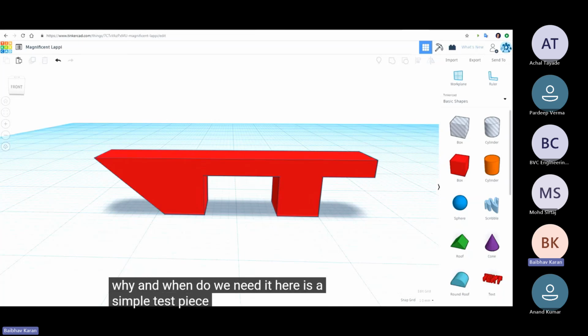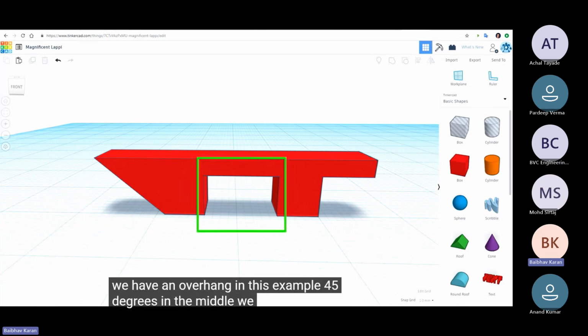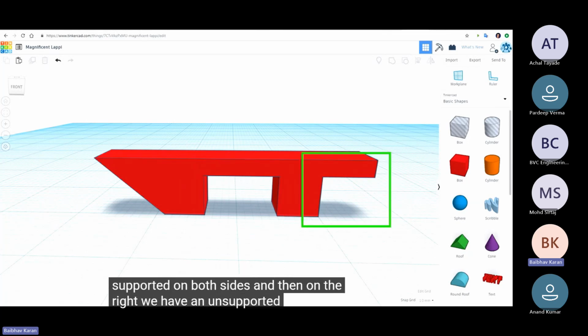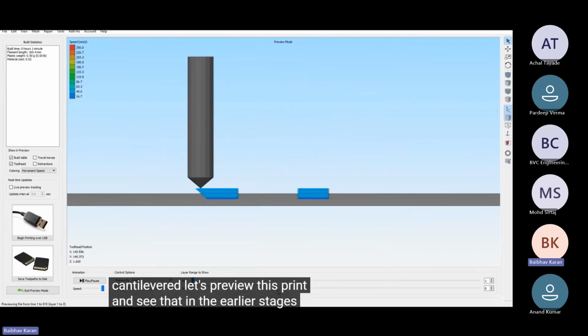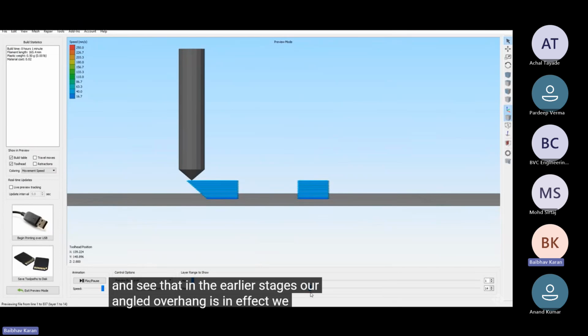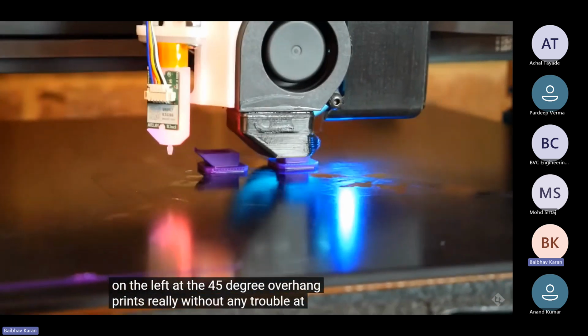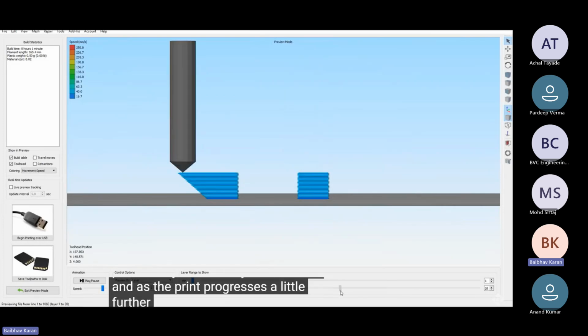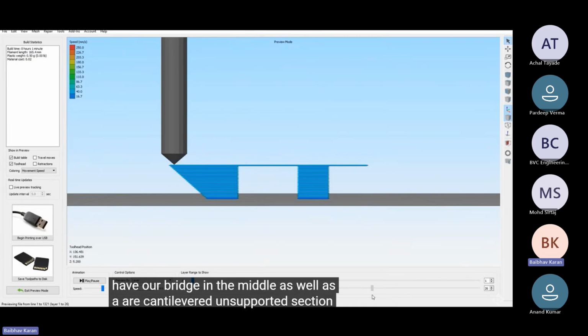Here is a simple test piece to show what a 3D printer can and can't achieve when building up layer by layer. On the left, we have an overhang, in this example 45 degrees. In the middle, we have a bridge supported on both sides, and then on the right, we have an unsupported section cantilevered. Let's preview this print and see that in the earlier stages, our angled overhang is in effect. We can see on the left that the 45-degree overhang prints really without any trouble at all. And as the print progresses a little further, we can see that we're going to have our bridge in the middle, as well as our cantilevered unsupported section on the right.